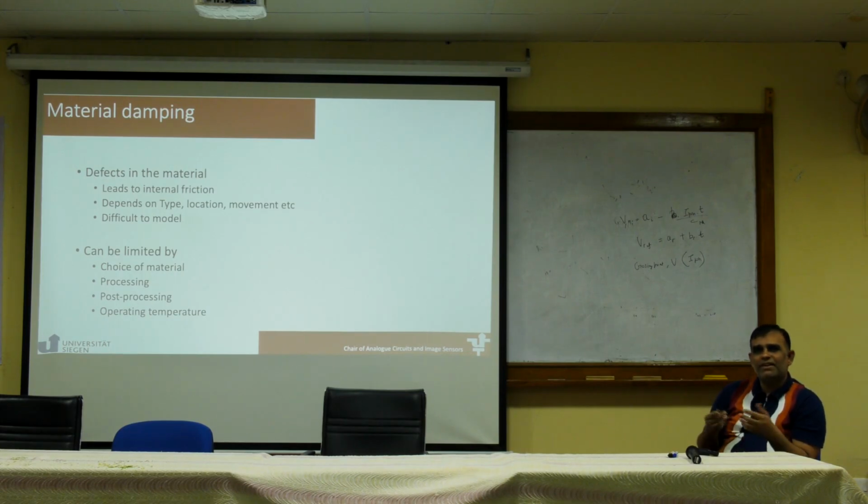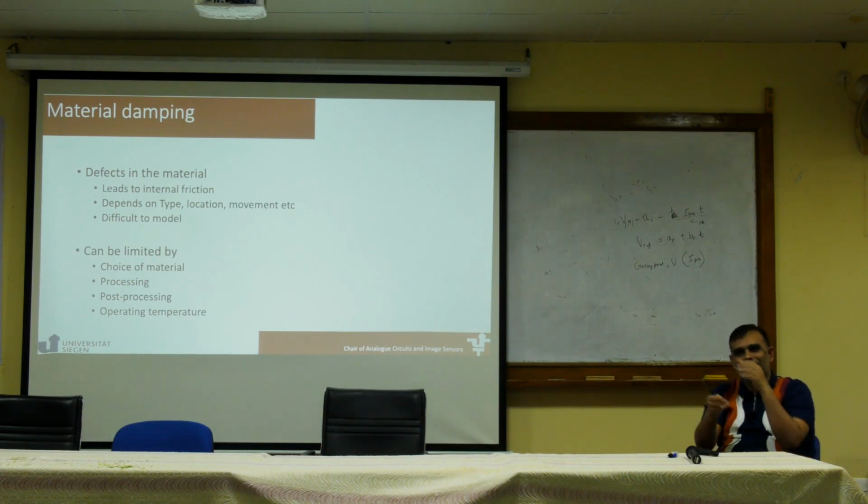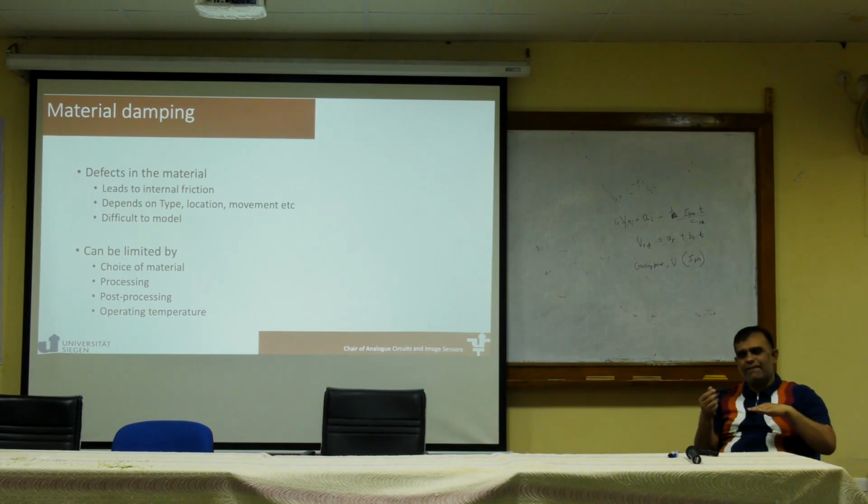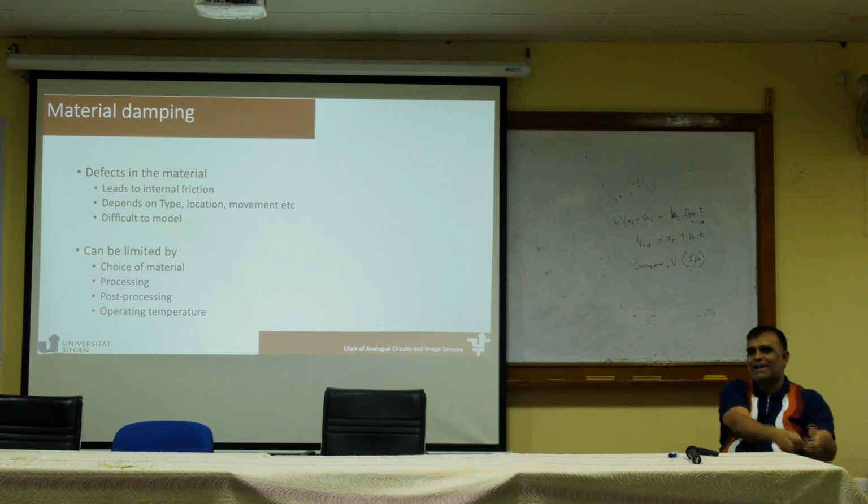Then we thought, oh, that works brilliantly. Why can't we use it as a biosensor? Remember, we did the biosensor calculation. So I took my resonator to a colleague in Ireland, and they said, but our solution is in liquid. We have this mRNA or bacterial solution in liquid. So we coated our sensor with some reagent, and the idea, which I thought was, okay, we take my resonator into the liquid, let the reaction take place, let its mass change. I will bring it back, put it back in the vacuum and measure its frequency change. So I measure the resonant frequency of the resonator, take it out of the vacuum chamber, let it react, bring it back to the vacuum chamber, and I will be happy, done.